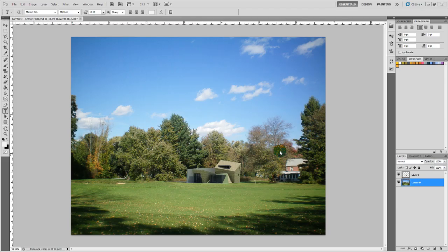This is a little technique I call high definition rendering. HDR toning is a tool within Photoshop. It started in CS5. CS4 has a version of it, but you need multiple images to create it. But HDR toning, you only need one image, and it's very, very powerful. I use it on almost all of my renderings for post-processing, and it adds a lot of depth, a lot of brilliance to the colors, and a lot of realism to your renderings.